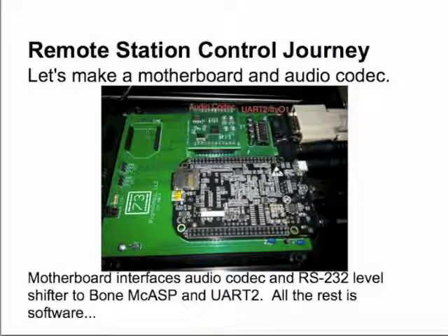He also has an AC relay if that's required, so you could use one of the smaller relays to turn on the AC relay, which turns on your power supply, and then you can turn on the DC relay to turn on power to your entire station. And that's all measured and monitored through the PIC, and it's polled every few seconds and displayed on the screen.